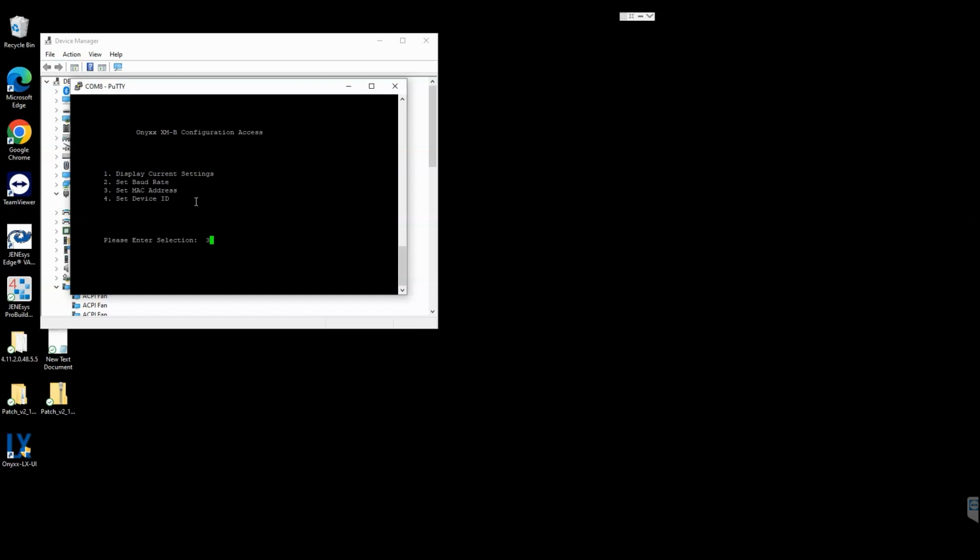Now the MAC address, I'm going to go ahead and hit address 6 here. And the reason why is 0 through 4, I don't necessarily recommend personally as MAC addresses to BACnet devices. Reason being is that there may be other BACnet devices such as routers and other tools that may take 0 to 4. So really kind of good common practice would be to start with 5, but I'm just going to do 6 here and hit enter.